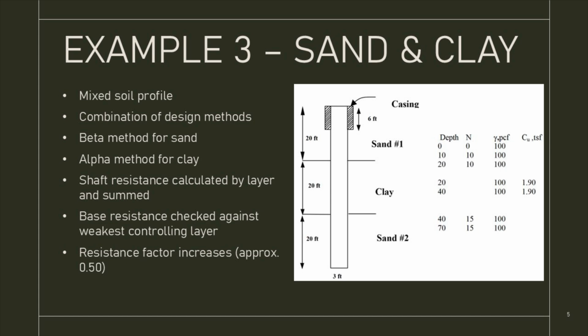A key design point here is that base resistance must be checked against all layers influencing the tip, not just the material directly below it. The weakest controlling layer can govern performance. Because multiple mechanisms contribute to resistance and the profile is well defined, the resistance factor increases to around 0.50.